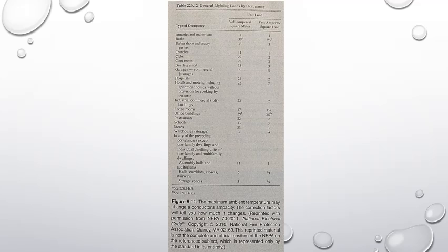The circuit requires 50 amps, and after multiplying by the adjustment factors, the 8 AWG wire is too small. You can select each size above 8 AWG to calculate the ampacity to find an adequate conductor. In this example, the current carrying conductor for the range was the only one adjusted. The other current carrying conductors in the raceway should also be adjusted to ensure a safe system.